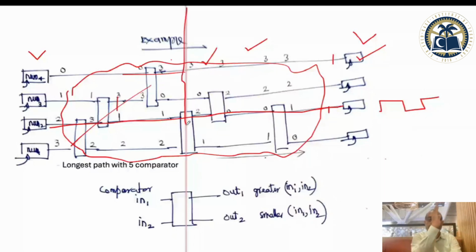Means okay, I'm going to put a register here. Sometimes it is not convenient to put a register in something which is actually computing. So then you can compromise with a little imbalanced partitioning. This part will have three comparators, this part will have two comparators, but you have very neat and clean pipelining. Getting inside a computational block and pipelining it sometimes becomes challenging.